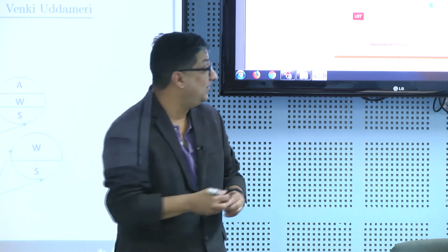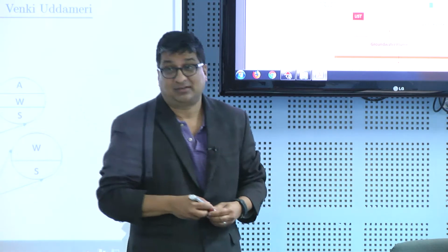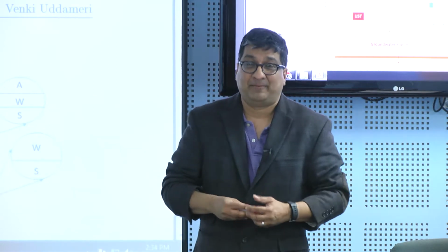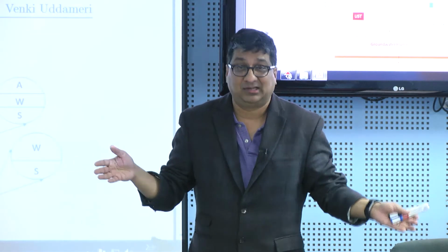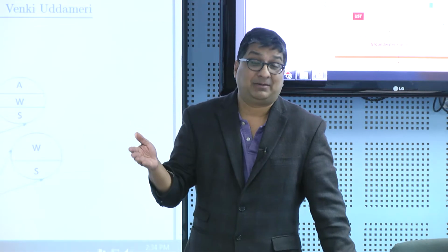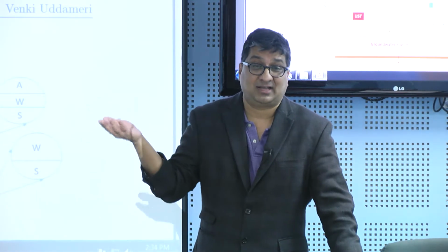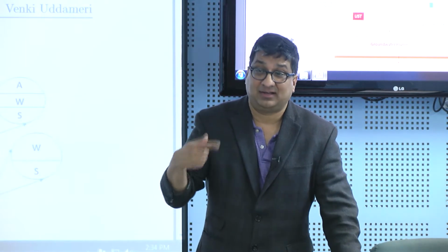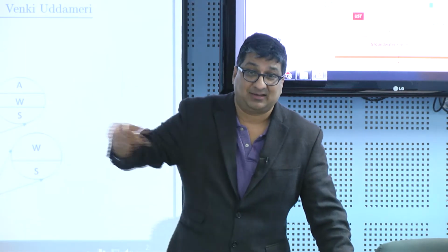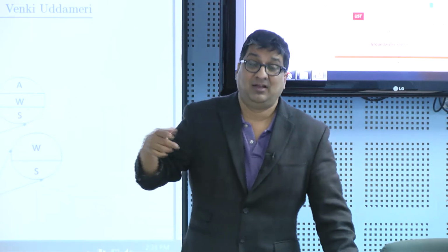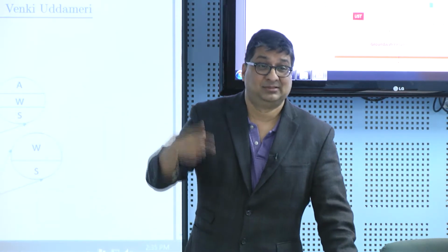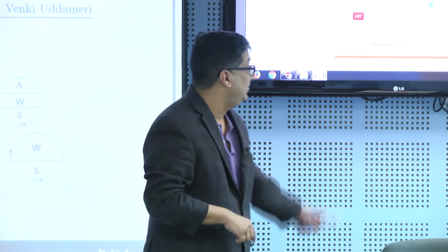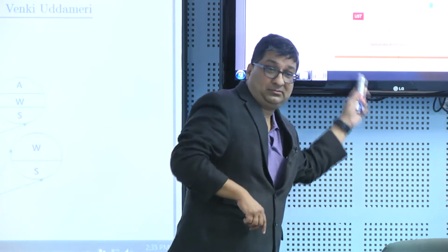Correct. So this is what we call a mixed flow reactor, or a plug flow with mixing, because it moves like a plug flow. Plug flow means there is no mixing whatsoever. When would we get plug flow? When the velocity is high or when the velocity is low? When the velocity is relatively high, the water just shoots like a jet, so there is no mixing taking place. On the other hand, if the velocity is low, now you have time for diffusion, you have time for mixing, so you can get some mixing going on here.